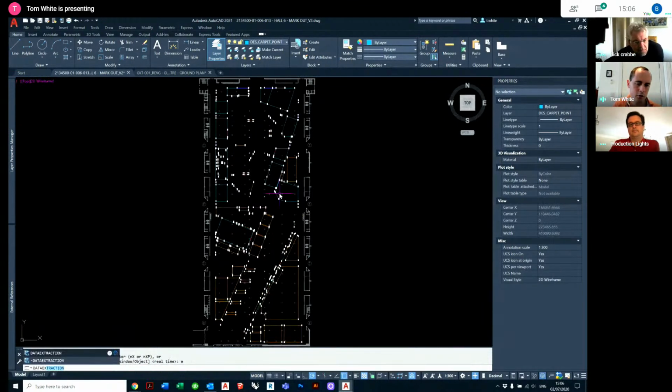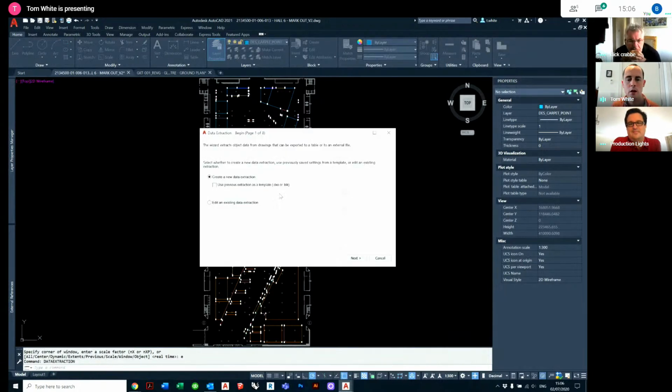So in AutoCAD for the last 3 or 4 years, if you start writing a word, often as long as it's spelled vaguely correctly, the rest of the word will be automatically filled out for you. And as soon as that's the case, you can press enter, and it will open a dialog box of that command. In this circumstance, it is data extraction.